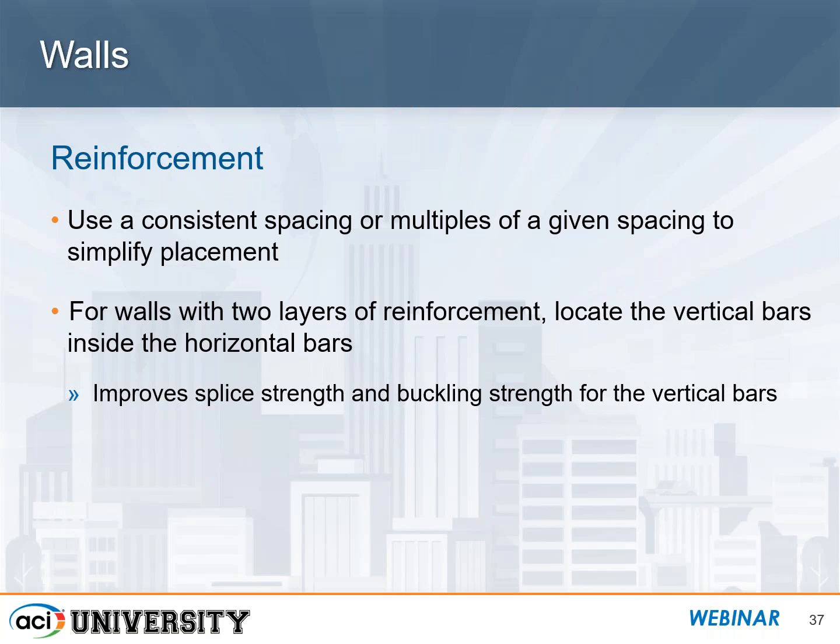But if you do it the other way, where you put the verticals on the outside and the horizontals in the inside, that's fine as well. We just sort of recommend this because we've seen things done in the past where this type of arrangement usually performs a little bit better. Not mandatory though, by any means, especially not ACI 318.